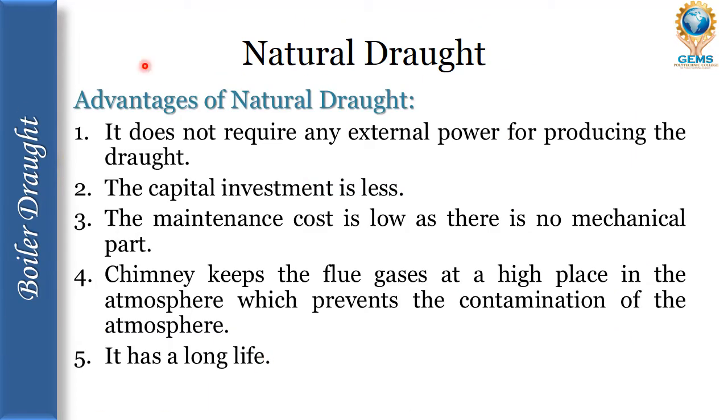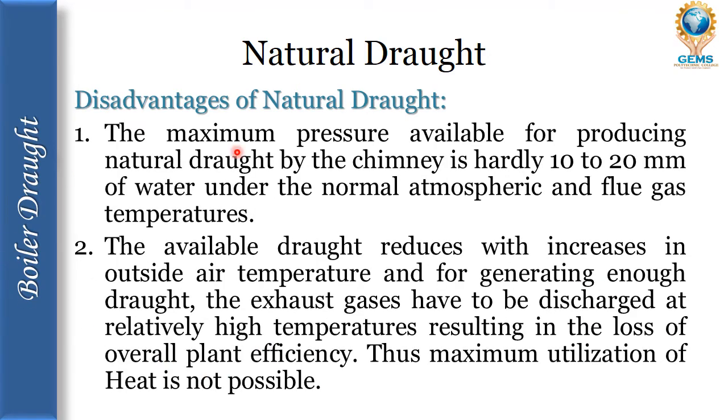What are the advantages of natural draft? It does not require any external power for producing the draft. The capital investment is less. The maintenance cost is low as there is no mechanical part. The chimney keeps the flue gases at a high place in the atmosphere, which prevents the contamination of the atmosphere. It also has a long life.